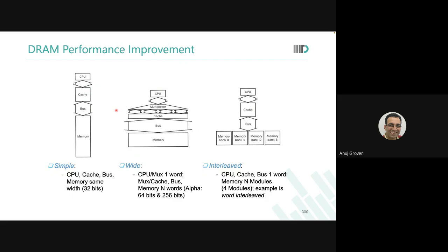The number of pins in the output bus would have reduced. Interleaved means allowing late read and early read and everything so that I can juggle with the same number of pins. And I could have kept it as wide. Typically making it very wide causes performance loss, because RC delays increase. And area you lose.